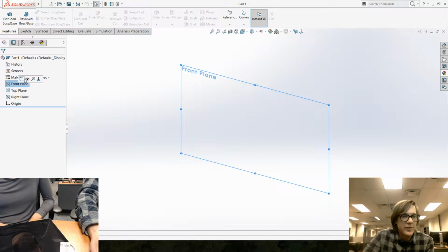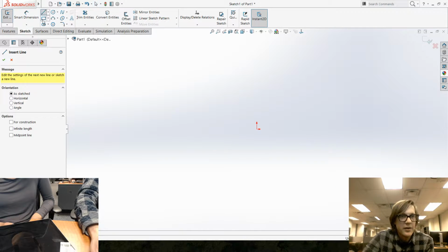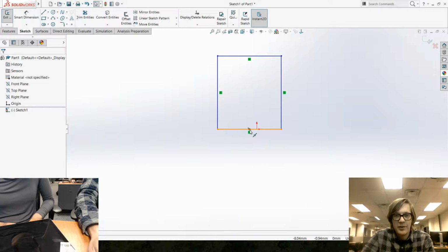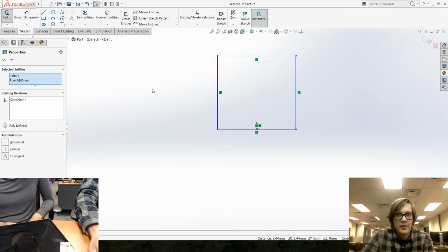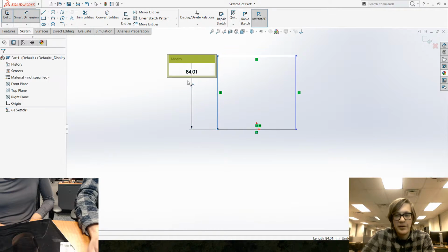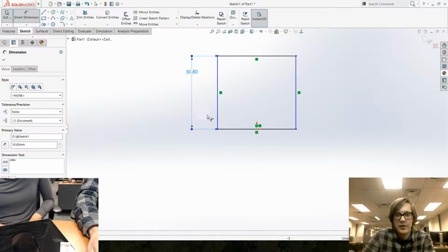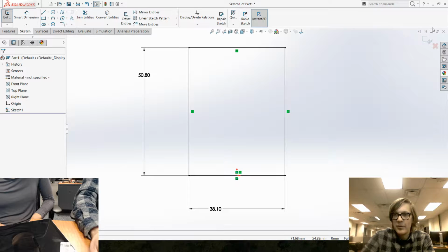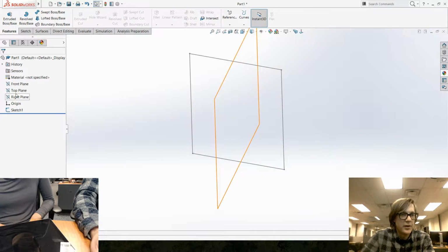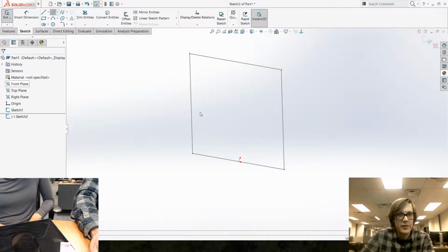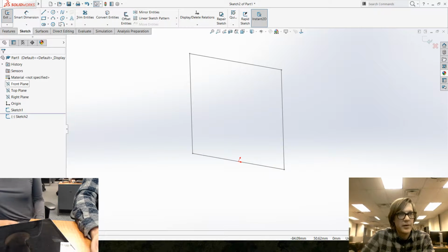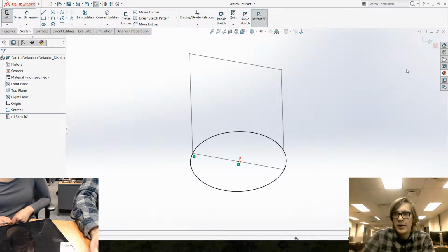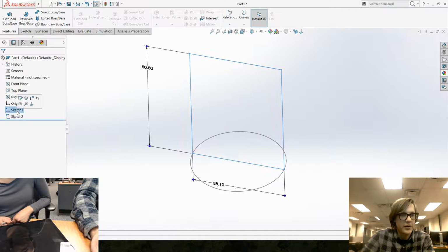Okay, so first things first, we're doing Votive Candle. I'm going to make a reference here really quick to show about how tall this should be, so like 2 inches and about 1.5 inches in diameter. It shows up in millimeters. Cool. Top plane. I'm also going to do a little reference. All the lines are black, which means I should be good to go.